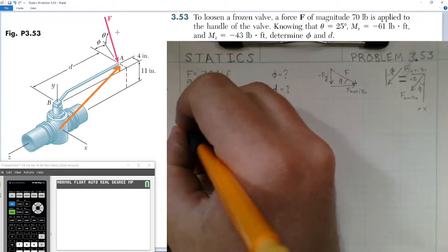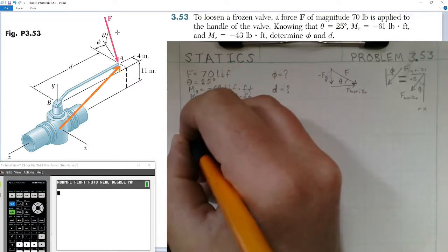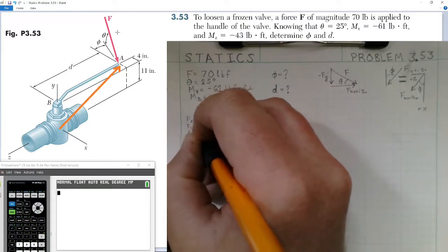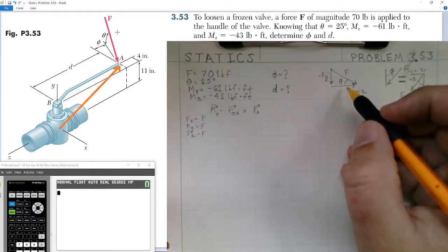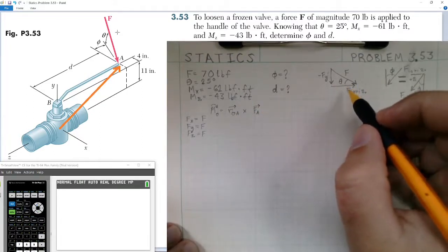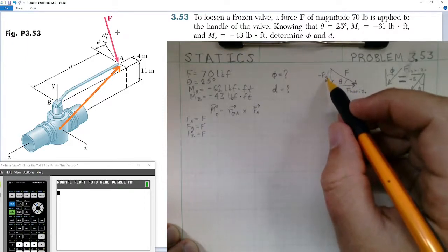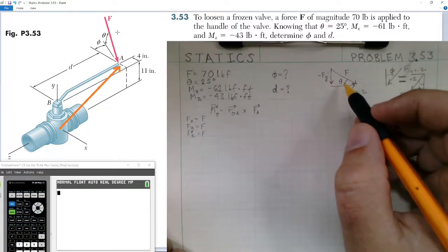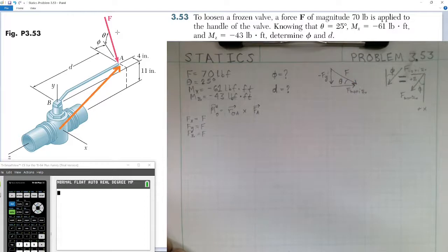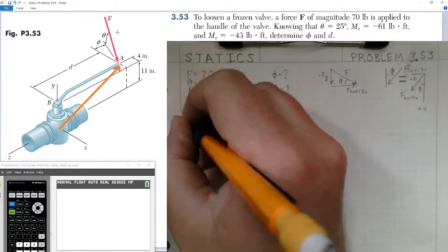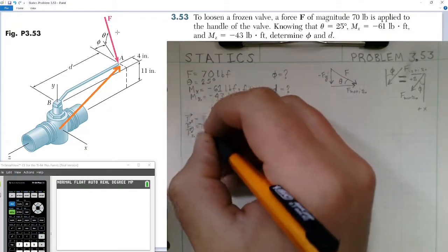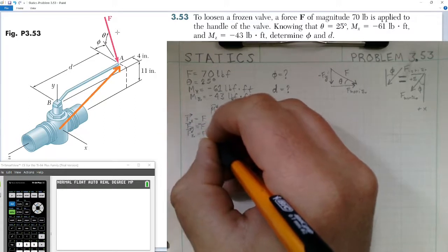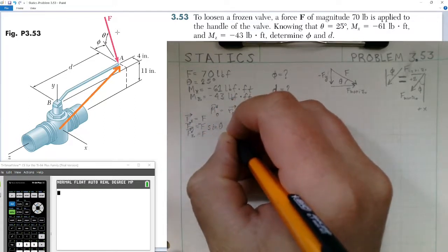Next, we're going to go down to the y, though. The y we can figure out first, and then the z will go from there. So, in the y-axis, we look at how it breaks down in a 3D view, as well as this 2D drawing. We have Fy pointing down in the negative j-hat direction, times the sine of the angle theta. So actually we'll write these all as force vectors. We can include the sines with these components. So it would be negative F times the sine of theta in the j-hat direction.